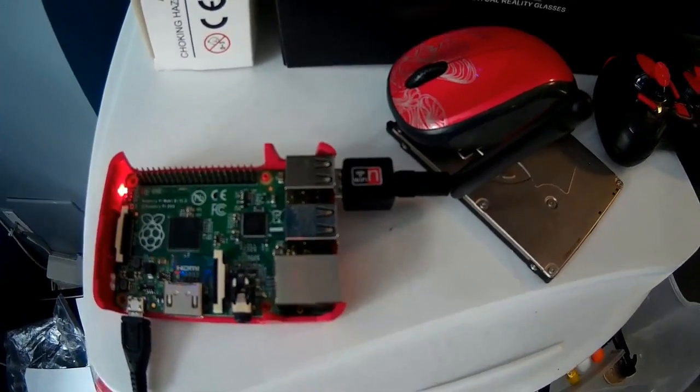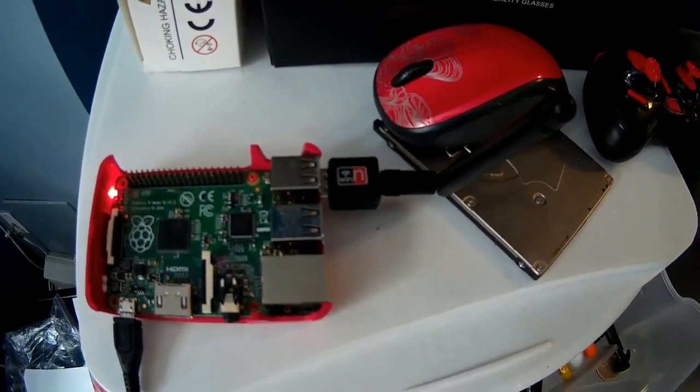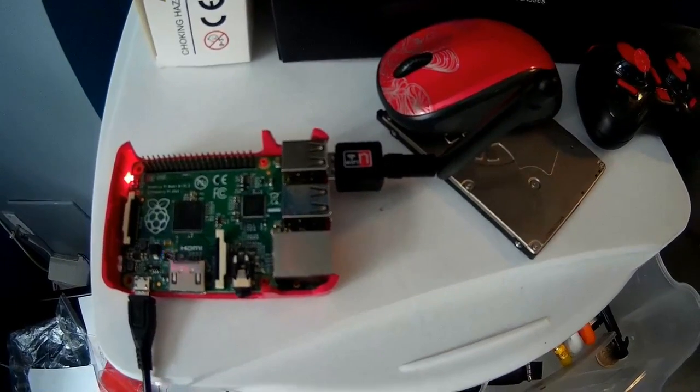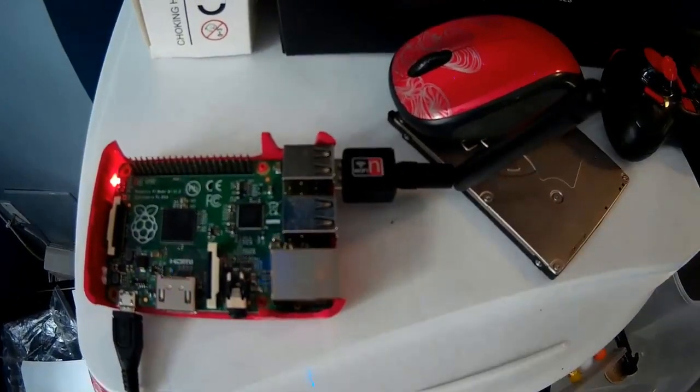Here's the Raspberry Pi that hosts the web page and the MQTT broker. It's connected to Wi-Fi via a Wi-Fi dongle. The project uses generic 5-volt power supplies, which supply power to the LEDs and the Mega separately.